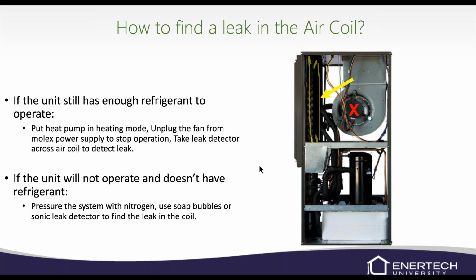Sometimes you can get it to bubble up, but that microchannel air coil is pretty thick, and so a lot of times it doesn't want to bubble up. When I think that there's a leak on one and I just can't find it, and I've got the coil back at the office, I've got a tank. I'll drop it, I'll plug up the lines, fill it with nitrogen, and I'll dump it into a bath of water and look for air bubbles.